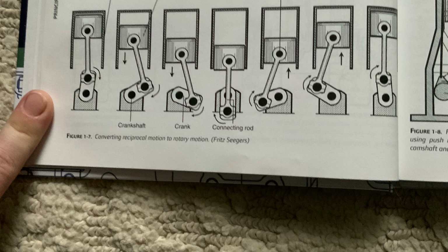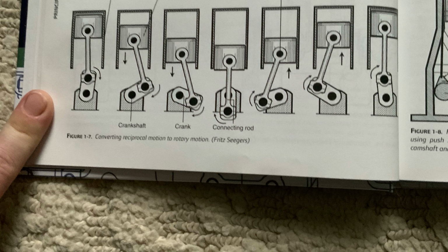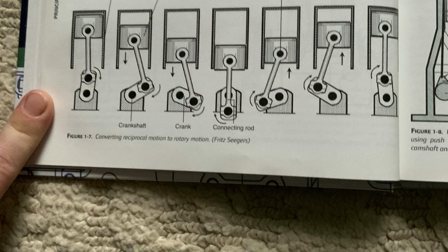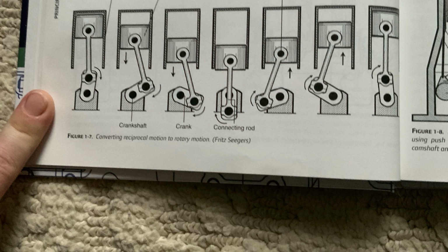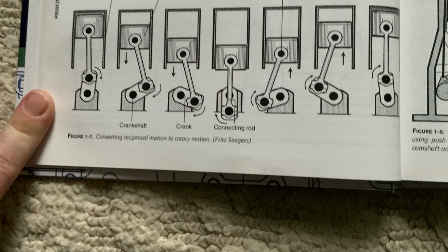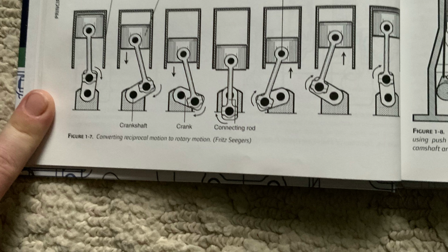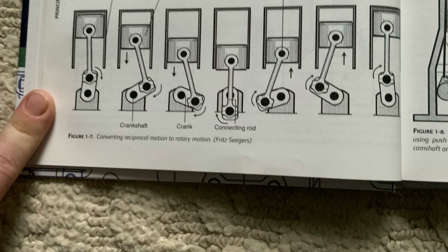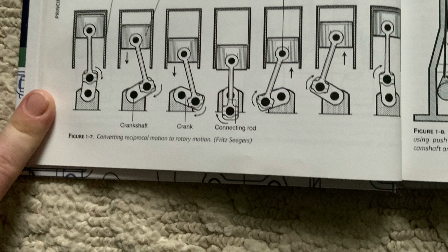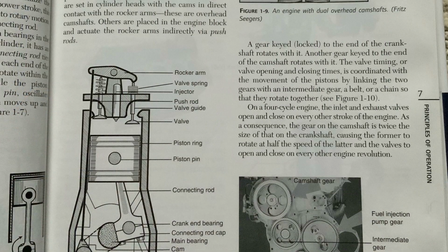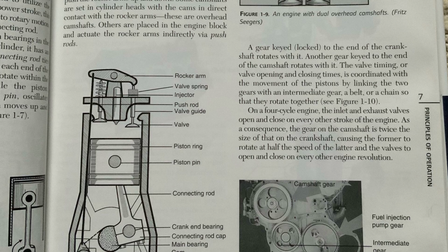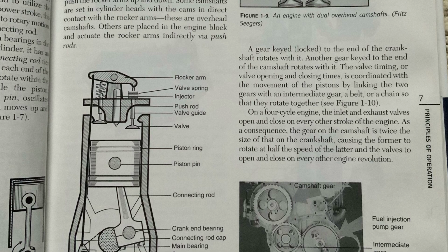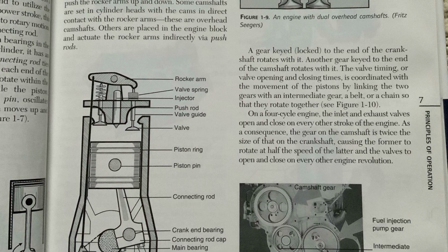Principal engine components. The crankshaft. So far, I've talked in a purely abstract fashion of a piston moving up and down in its cylinder. To harness a piston to the rest of the engine and to utilize the mechanical energy developed by its power stroke, this reciprocal motion must be converted to rotary motion. This is done by a crankshaft and connecting rod.